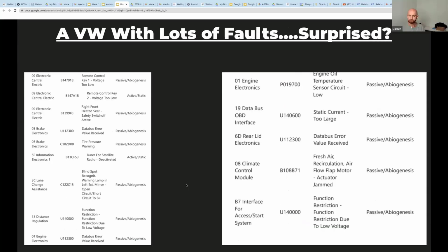So anyway, I told the shop, look, there's so many faults. And whenever I see a vehicle that has a ton of U codes and a ton of voltage related codes, the first thing I think is foundational electrical problem, right? Battery problem, voltage problem, something is going on here that's causing this vehicle to set all these codes. So I said, all right, let's look. Now, many of the scan tools that I worked with have a voltage display PID right up in the corner of the scan tool that you can see at all times when connected to the DLC. I picked up on that right away and I said, whoa, your voltage is real low. We're already dropping below 12 volts and we've been connected to this vehicle for like 30 seconds.